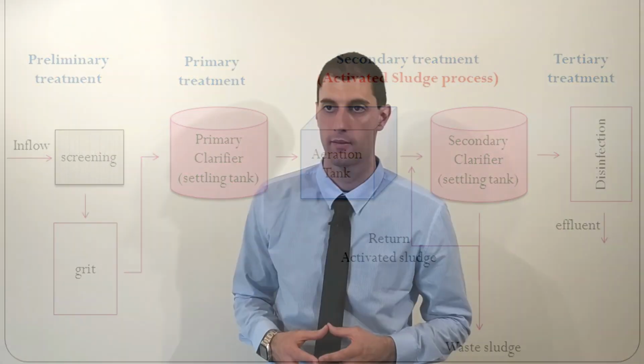Chlorine disinfects the water through chemical disinfection and kills pathogenic bacteria inside the wastewater, which is really important. The dose usually ranges from 5 to 20 milligrams of chlorine per liter. After the chlorination, when we have killed bacteria inside the effluent water, we have to remove chlorine from the wastewater with sulfur dioxide.